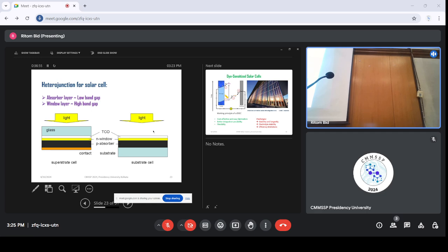Now if you use both N-type and P-type silicon, the light would not reach the junction as easily. Here, the transparent layer is called the window layer. So the light transmits through the window and goes to the absorber junction. So the electron hole pair generates at the interface where the built-in electric fields are. So the possibility of separation is higher, right?